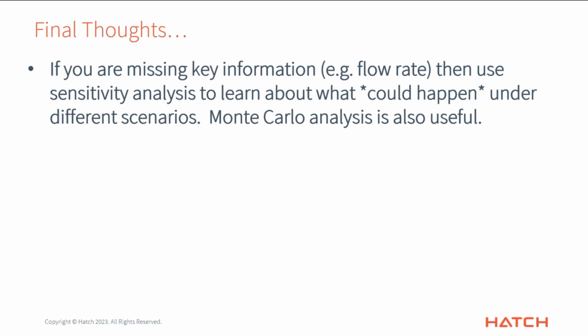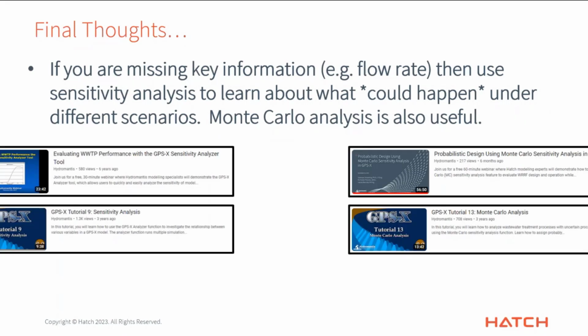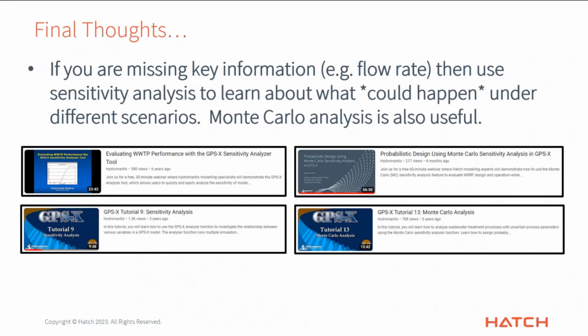So I'm mentioning Monte Carlo analysis here too. That's using probabilistic modeling. You run a large number of simulations. What's the percentage probability that we're going to get into trouble? That kind of thing. So we have many webinars on these particular topics, both regular sensitivity analysis and also using probabilistic design, using Monte Carlo in order to do analysis and optimization. So I suggest you take a trip through our webinars on our YouTube channel when you have a moment.